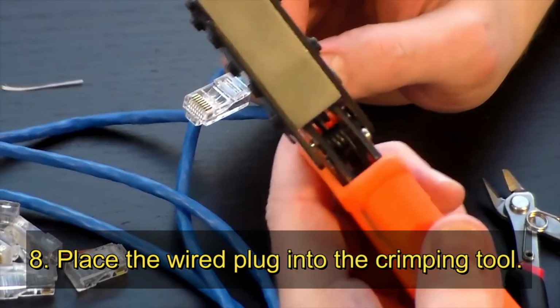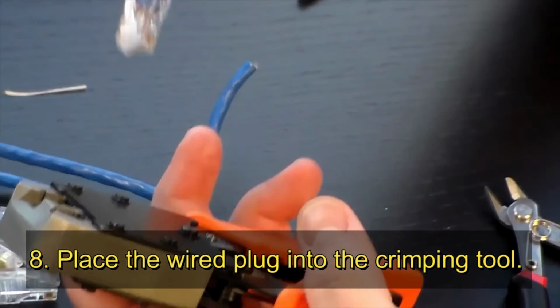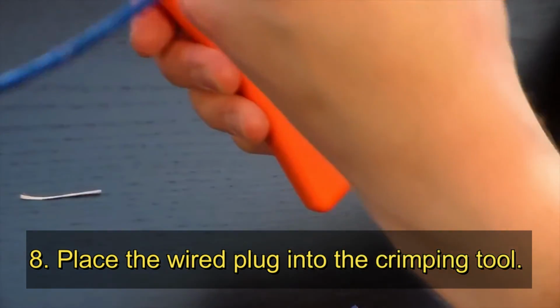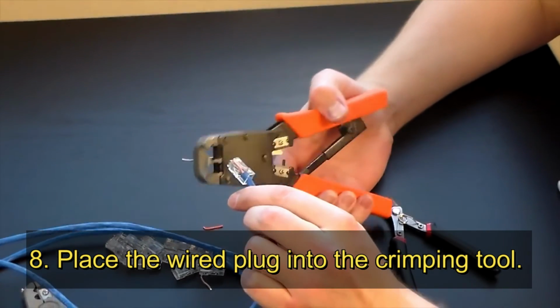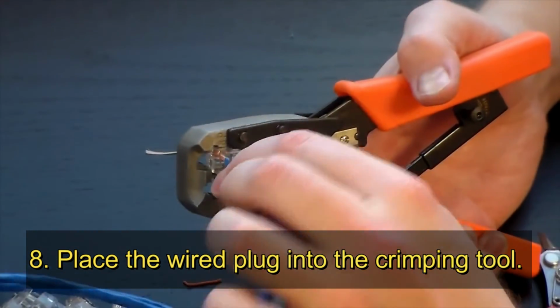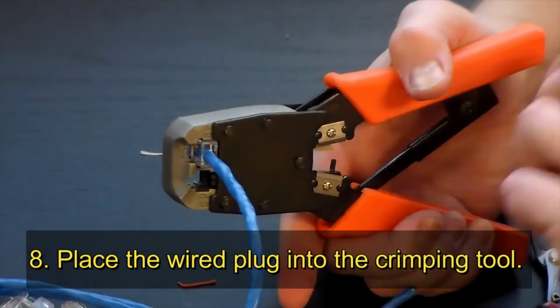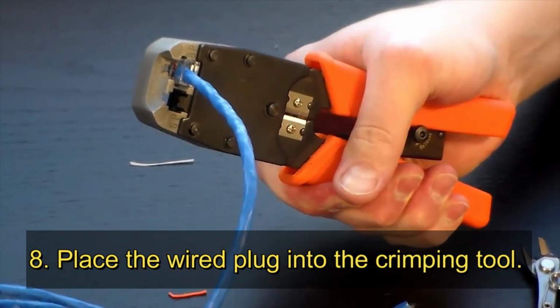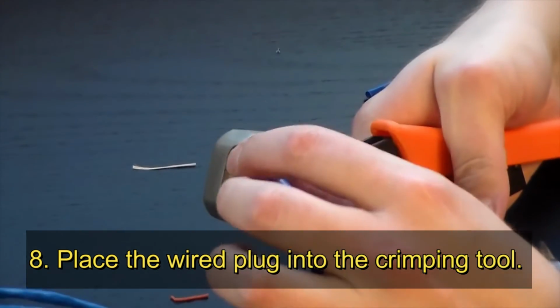Step number 8. Place the wired plug into the crimping tool. Give the handle a firm squeeze. You should hear a ratcheting noise as you continue. Once you have completed the crimp, the handle will reset to the open position. To ensure all pins are set, some prefer to double crimp by repeating this step.